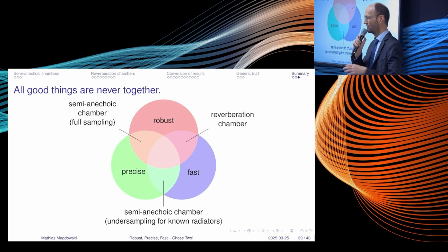not robust. The result depends on where you place the equipment under test, how the cables are oriented, will the cables go to the side and then to the ground, will the cables go directly to ground, what will be the termination of the cables, and so on and so on. So yeah, the perfect test unfortunately does not exist.